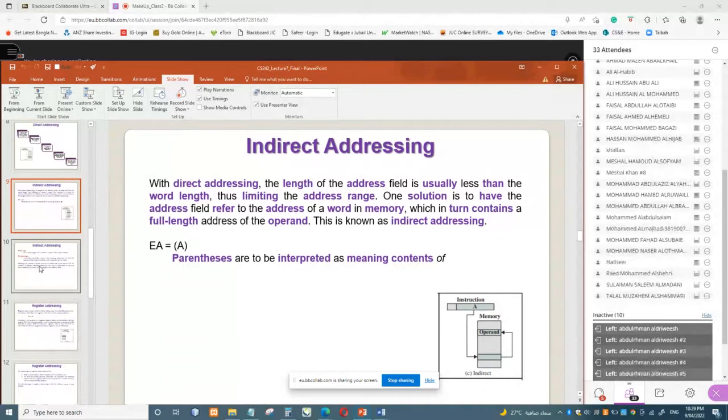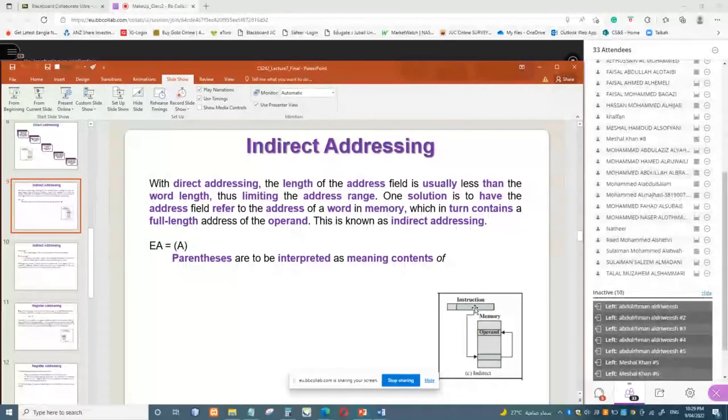We always use indirect addressing. Now, what is indirect addressing? In case of indirect addressing, we do contain some memory location, but the range of that memory location is within 1 kilobyte to 8 kilobyte, like that, because you cannot spend a lot of bits for your memory location.